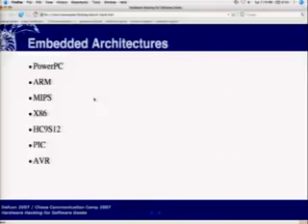Some of them will have secure ROMs where you cannot read out the ROM through anything once it's been loaded, for protecting IP, of course. This is true for certain values of cannot read out. If anybody caught Bunny's talk at ShmooCon 2 years ago, he basically depotted a chip, removed the plastic from the top of it, and then shone UV in at an angle to get under the aluminum layer that was covering the fuses that were set when the chip was set to be write only. And that way managed to clear the fuse and dump all the code out of the chip. Needless to say, that's not a very easy operation. It's doable, though. So, not something a noob should attempt. Yeah, he used a lot of acid for that to etch the chip top off.